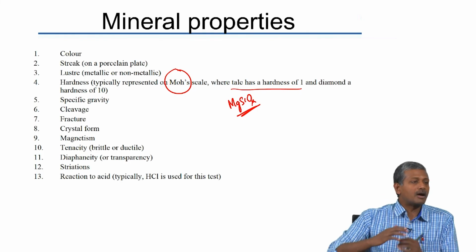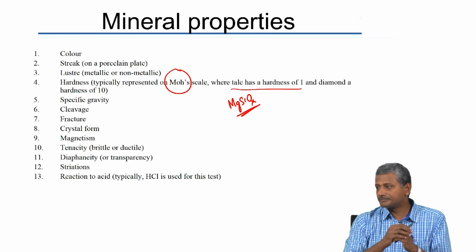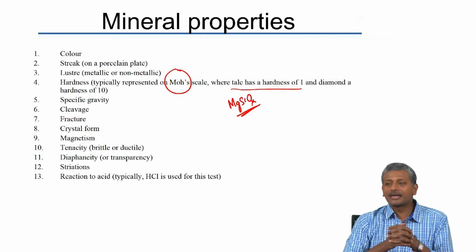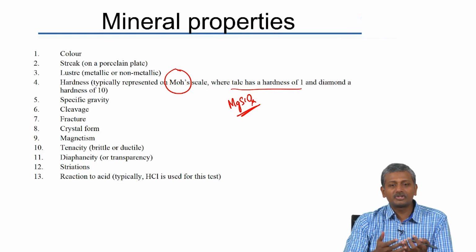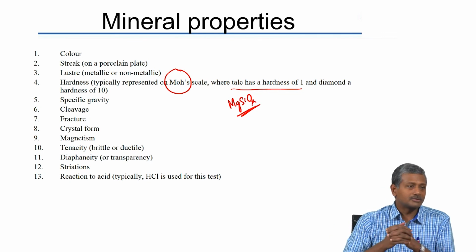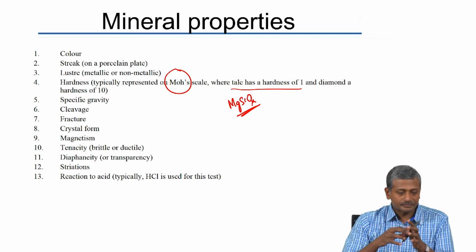That means going from hardness 1 to 2 is not the same as going from hardness 2 to 3. Okay, but what is the hardness of steel on the scale? About 6.5. 6.5 is the hardness of steel. Okay. Limestone or calcite have a hardness of around 3. Okay. And concrete, which is essentially made with the same component, is a little bit more than 3. It is between 3 and 4. Generally, that is the hardness of concrete, or cement paste rather.